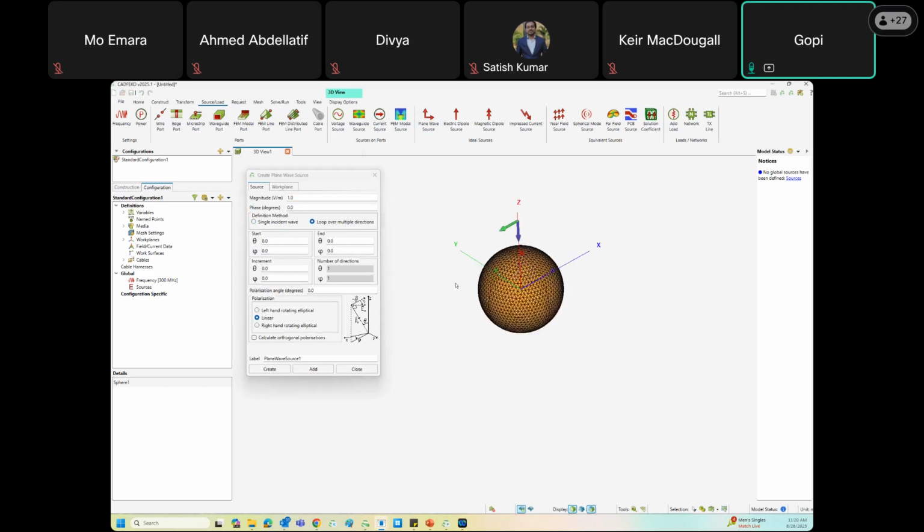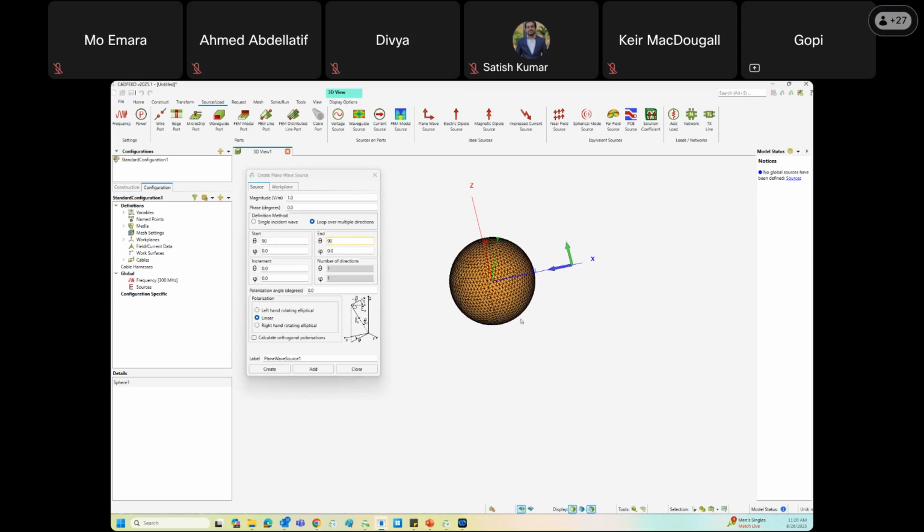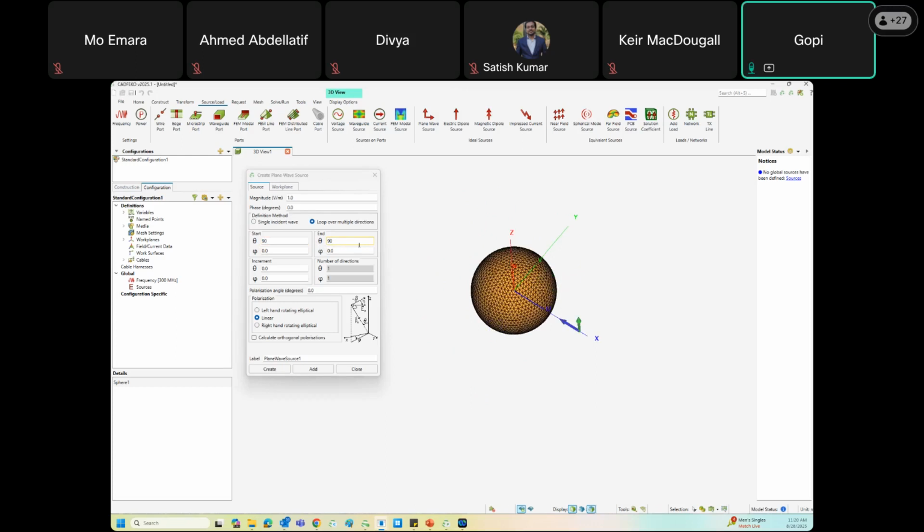Let's say you want to calculate RCS in the azimuth plane. Then along the z-axis, that's theta equal to 0. So to change the incident angle to the azimuth plane, you can change theta to 90. And let's say you want to sweep in the azimuth plane, then you can sweep your phi, for example 0 to 90 degrees.